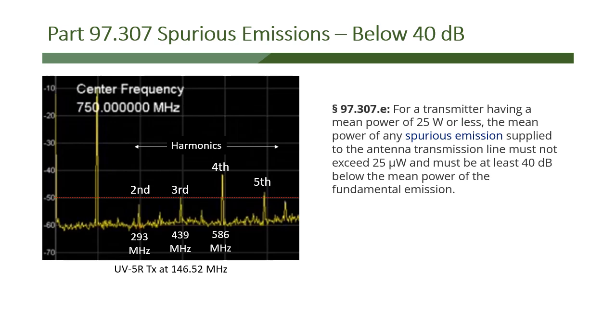Which means that when you have amplification going on or mixing going on to create the radio signal, you create products along the same time. So you can create harmonic products. And a good radio filters those harmonic products out, so all you're left with is the center frequency. That big spike on the left in yellow is the center frequency. That is the frequency of the transmission.